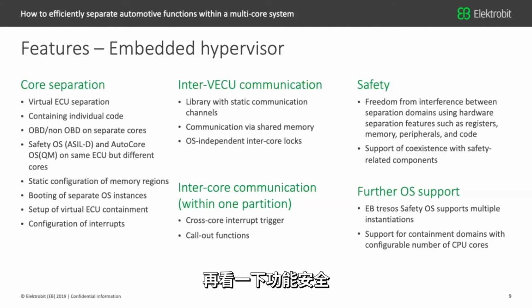Okay, then safety, I cannot stress that enough. For the freedom from interference between separate domains, using hardware separation mechanisms, I have register protection, memory protection, certain peripherals, and I can protect my code execution on the cores. So they are still available.